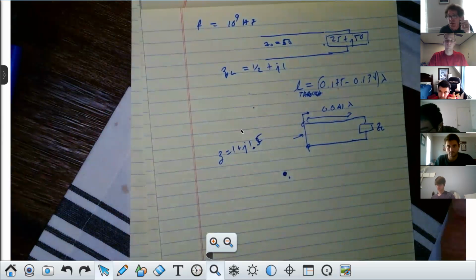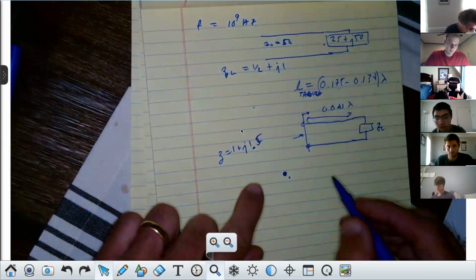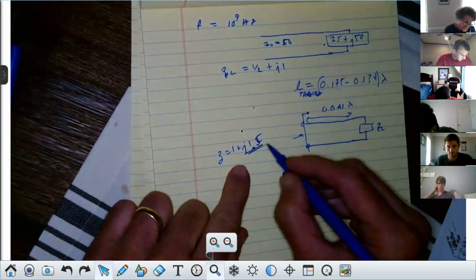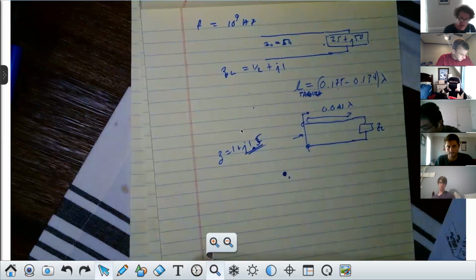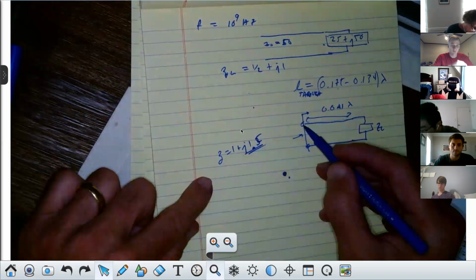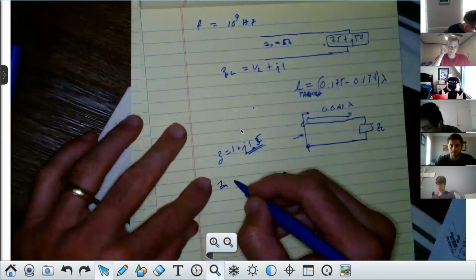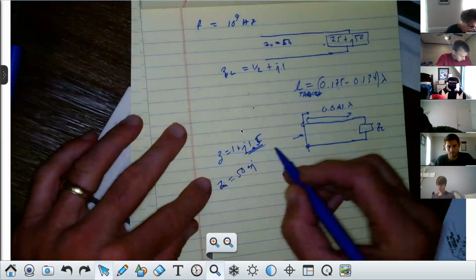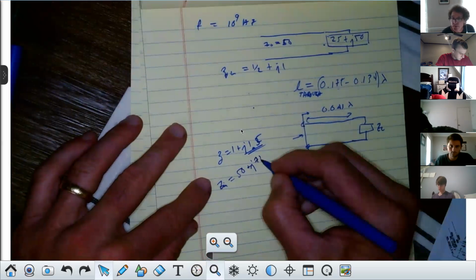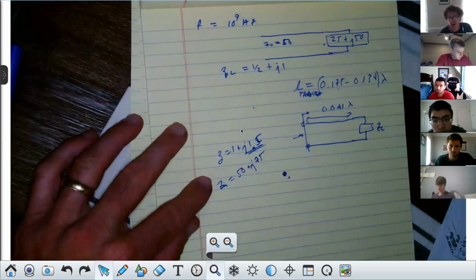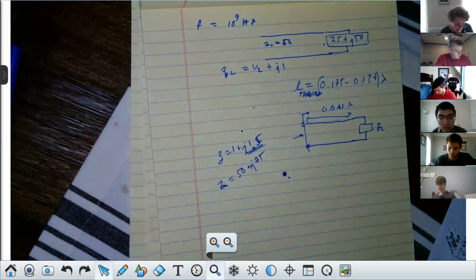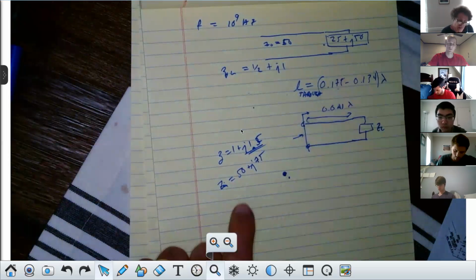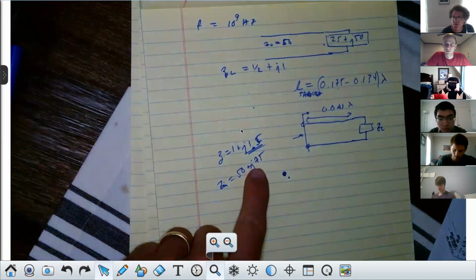Are you with me? Now, if we have that, we want to get rid of j 1.5. So first, this is the way I do it. Calculate the actual impedance at this point. So the actual input impedance, Z in right there, would be equal to 50, because it was a 50 ohm line, plus j, well, 1.5 times 50 is 75, isn't it? You all follow me? I'm calculating the actual impedance at a distance of 0.041. The real part is 50, the imaginary part is 75, correct, class? I want to get rid of this j75.